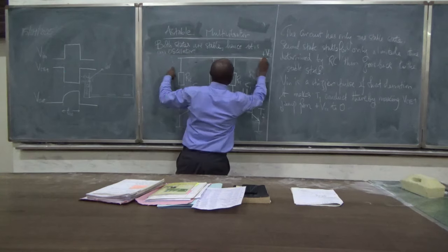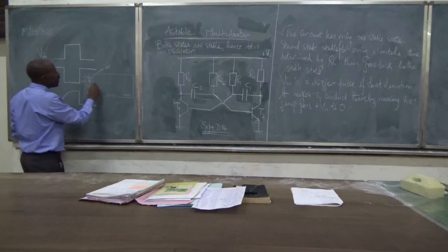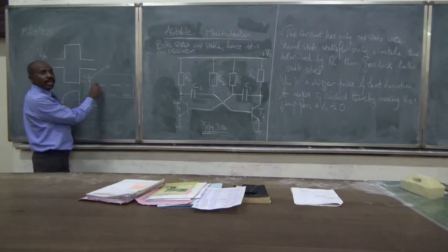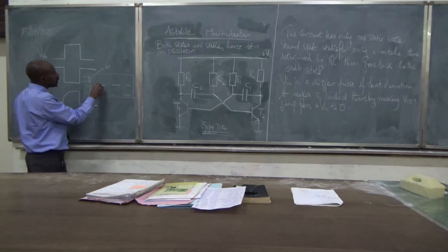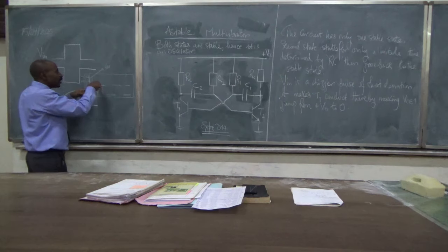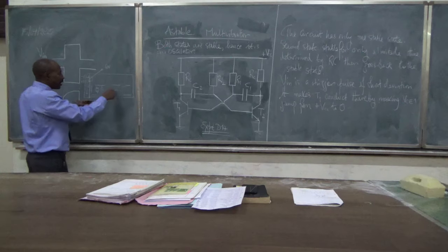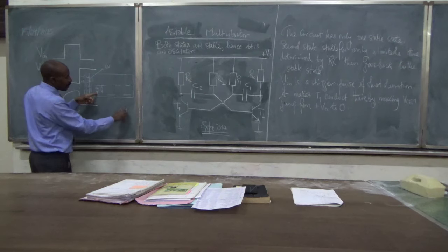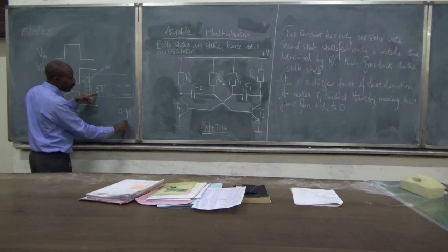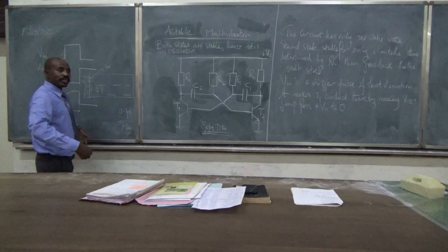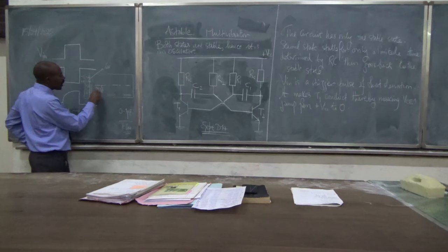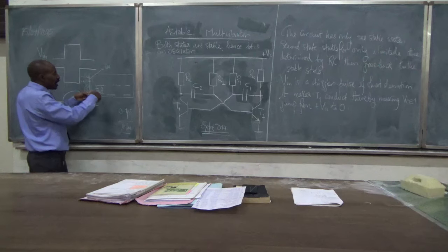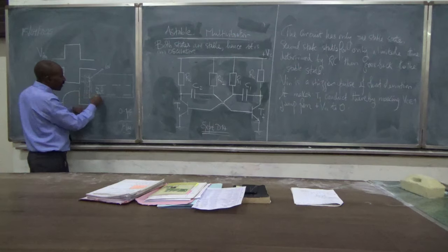So along this line here, I would wish you to use any of these reds inside here, and then you put the resistances as they look in the diagram. So you put the other legs in the holes along the red, and then you put the yellow capacitors, the 0.01 and the 0.1 microfarad capacitors, which are very big. You put one leg here, the other leg there, and then finally you go to the transistor.